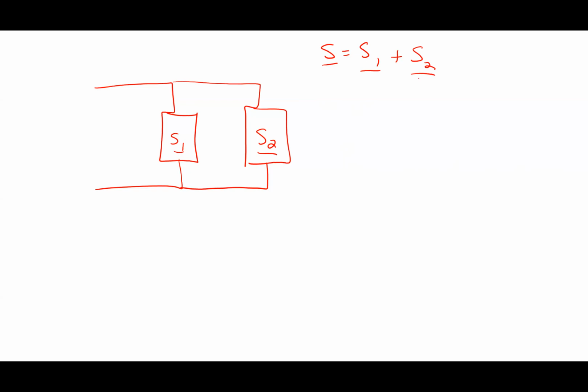If I add those two vectors, this works out to be, you can go back and look at it later, 21 kilowatts plus j times 11.796 kVARs. Now, what I want is to make the power factor of that combination unity.